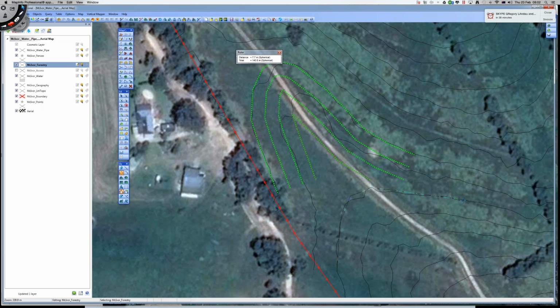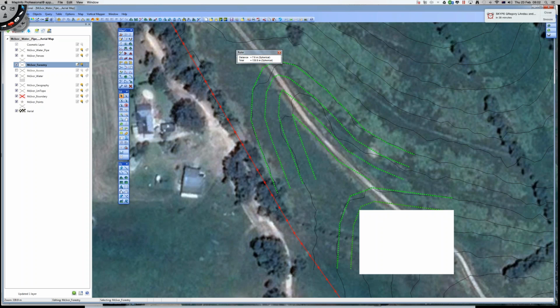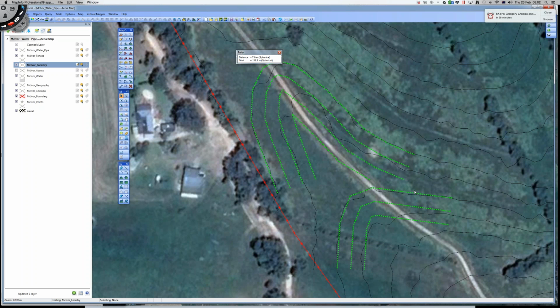You start to see when you're drawing why you wouldn't go click, click, click, click. You'd just create a lot of work for yourself in taking out nodes afterwards. Now I'll go up 10, and off we go. With this whole thing, you can very quickly see if your pattern is doing what you want it to do. You can see here I followed that contour, I've gone up the slope. That point there is higher than that point there. With that, you can say with confidence, I'll continue to use this guideline that I had set at the bottom.